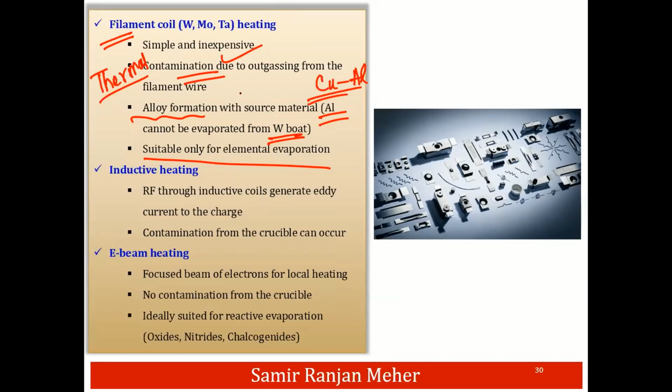Alloys cannot be evaporated, and we should have to choose the proper boat. The other way is through RF induction heating. But again, in this case, because it is based on eddy current, contamination from the crucible can occur. So that also we need to take care.